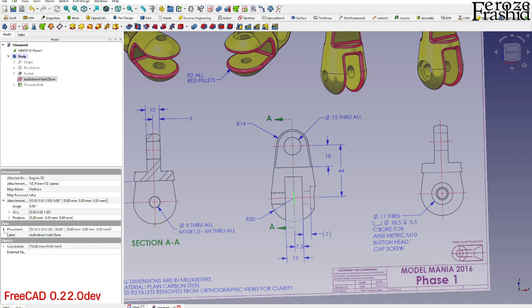So now, not in the placement though, right? If it was in the part workbench and I'm moving some sketch or object, it would be in placement. But here in Part Design, the sketch moves from attachment, and on the Z, there's a local distance in Z, and I want to move it on 20.